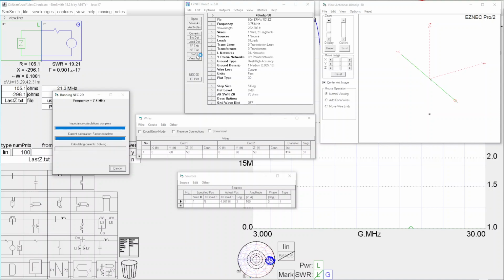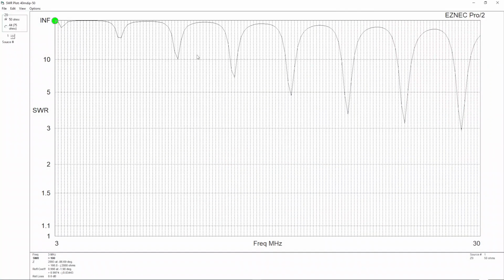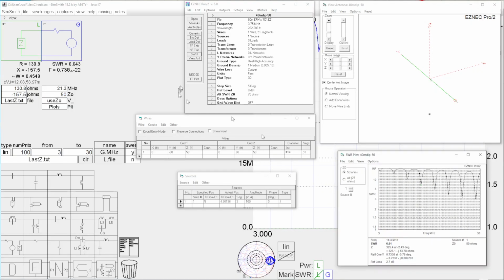And like I said, the tuner will actually change the electrical length to get it to look like there's a perfect matchup of an integral number of these half-wave standing wave loops on your antenna for that frequency. And that's the key. All right. So now this one's down here at 10.8. This one's at 7. This guy here is at 14.4. Pretty darn close. Okay. So let's minimize that.